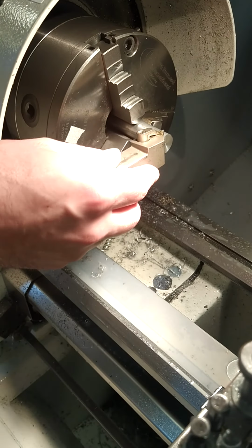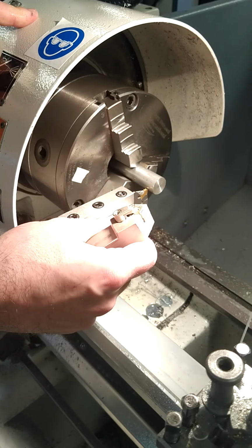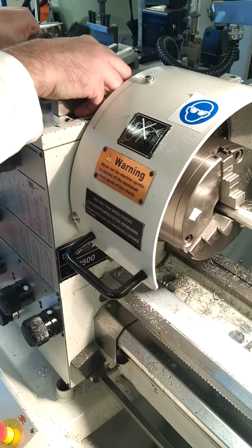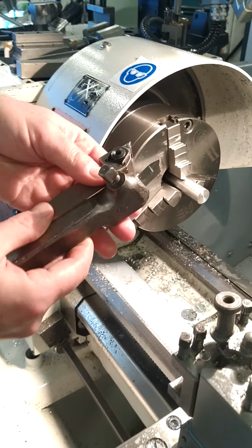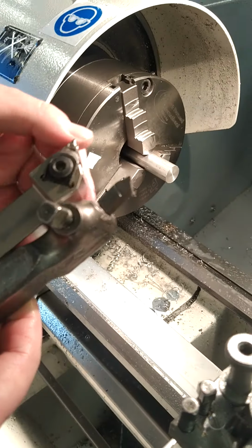That's what we call a carbide cutter, and that's for doing 45-degree chamfers on the edge of the part. This tool here is what's called a parting off tool, and that's used for cutting grooves into the part. This one is just a difference: it's high-speed tool steel, a different material completely to the carbide cutters.